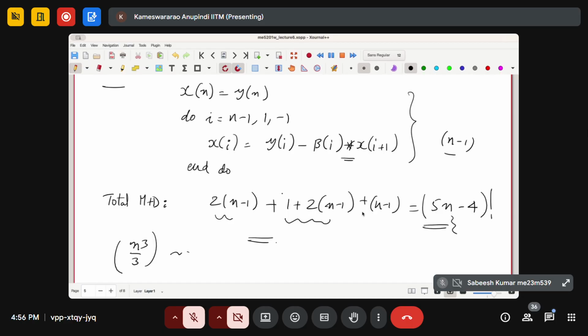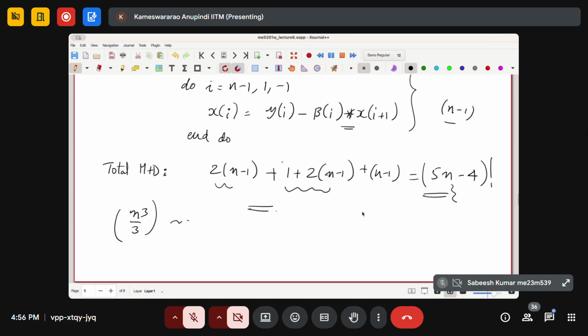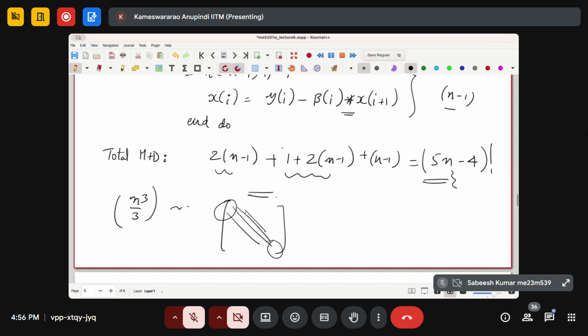So in FEM, I may not say all the time you will get banded matrices. It is possible that you will get banded matrices. You may get little denser matrices also, depending on the shape functions you would use. But still, when you form the global matrix, you will get a kind of banded matrix, which you probably have experienced. Now, these boundary conditions are actually only limited to some places. We are talking about, let us say, the full matrix. Your boundary conditions might be affecting only somewhere here or here or here, depending on the cells, but they may not be affecting the total structure of the entire matrix.